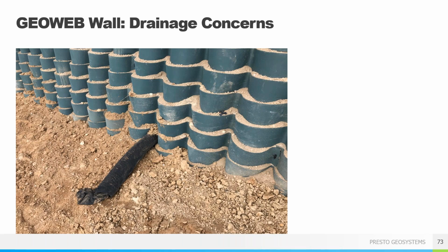So you want to design it with a minimum slope to make sure that water flows freely. Another key item here is to make sure that the pipe doesn't stop at the front face of that wall. You want to make sure it extends out past the wall a couple feet. If there's going to be some erosion here, you account for that, whether with splash blocks, which I've seen a lot of engineers use, or riprap with non-woven geotextiles. Just make sure that you don't end it at the wall and then it starts to scour and undermines the front fascia of that wall.